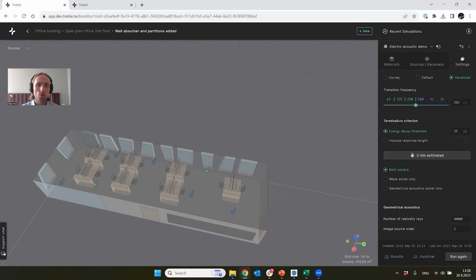So typically when people do room acoustic simulations, they have needed up until now to set the impulse response length of the simulation, how long of a simulation impulse you should simulate. This means that you have to guess beforehand roughly how long you think the IR is going to be. If you put it too short, sometimes you don't get, for example, the T30 reverberation time values, because you don't have enough energy decay in your impulse response to calculate T30.